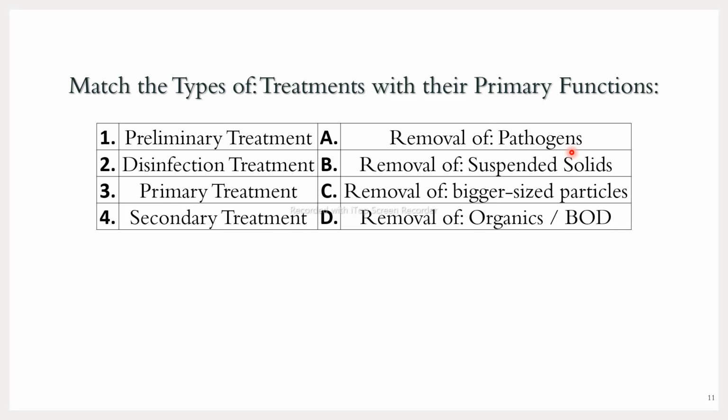So chlorination is suitable for countries like India, where after the water is pumped from the municipal or other sources after treatment, it goes via various kinds of networks, and these networks flow through various places, underground or whatever. So if there is a leakage in the pipe, then pathogen can come into the water. So after the treatment, if the pathogen comes into the water, chlorine has an effective action because chlorine has a longer life. Otherwise, once the disinfectant gas is injected inside the water, it may come out, right? But chlorine stays in radical form in water for a longer period of time. So that's why it is suitable for developing countries like India.